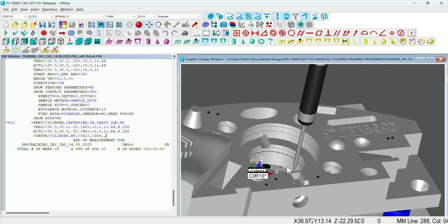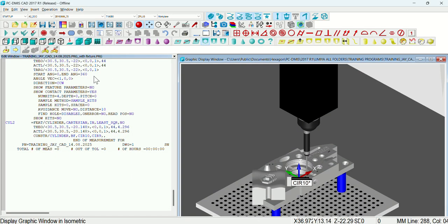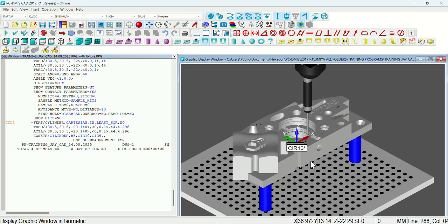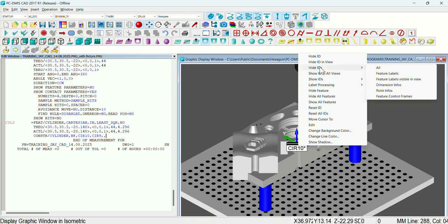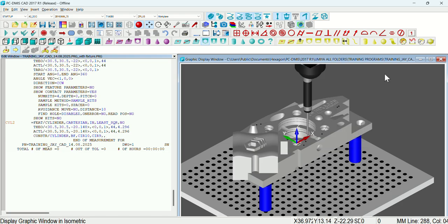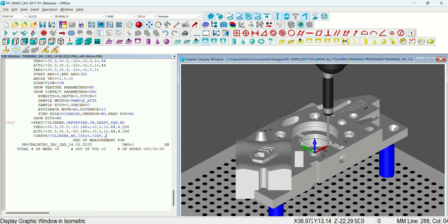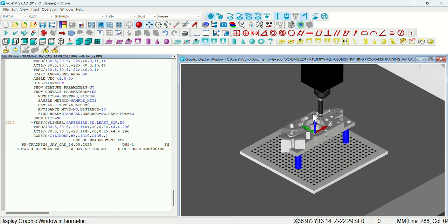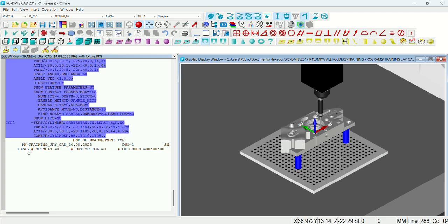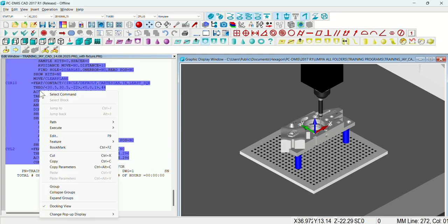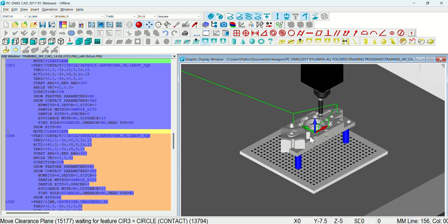That's it for today. So again we'll run our collision detection to see whether there is any collision in the newly generated features or not. Okay, so let's go to the keyboard, press Control and then press A. It will select all. Just right click, go to path, collision detection. So now every feature will be in automatic mode. It will run.